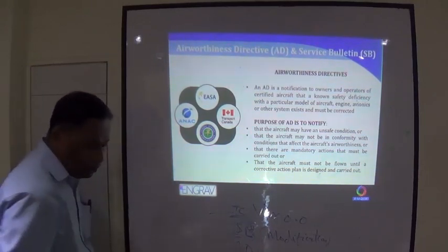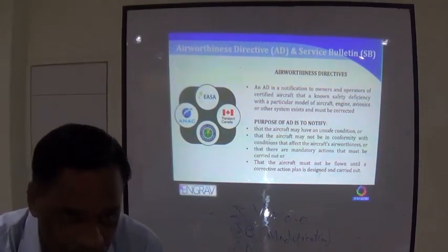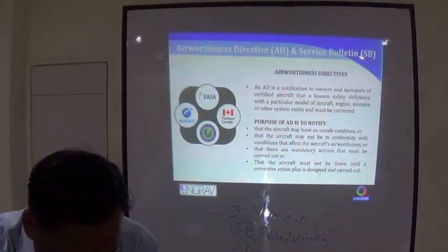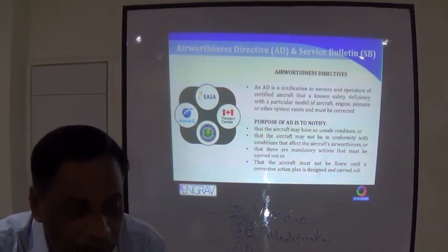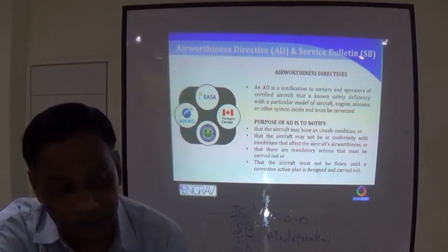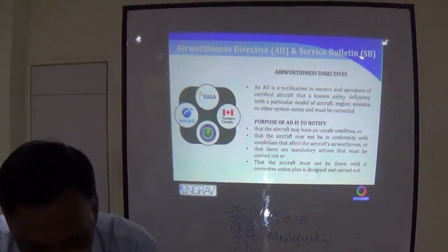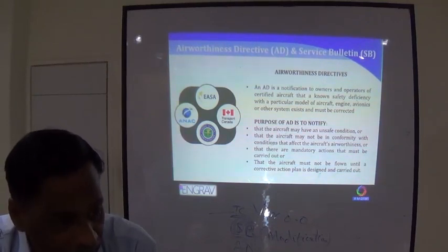When the regulatory authority walks into an airline for an audit, which they periodically do, one of the first questions they ask is, show our maintenance program compliance, those 1,500 tasks which I was talking about. They want to see whether any overflying has happened. Second, they will say, where is your AD list?